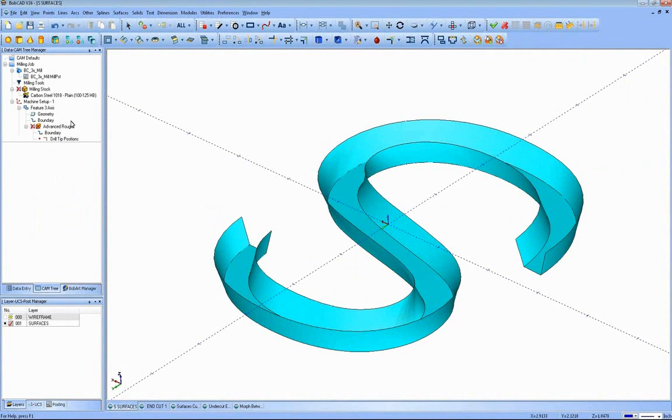But what I want to do is unblank a standard advanced roughing toolpath to show you how this one would go through here and some benefits of using the multi-axis over this one as well. As you can see, the advanced roughing is going to follow the shape of the channel, but it also turns. So if this was a wall, or if you wanted the tool to come out the side of this, you would have to extend it out, and it's going to turn.